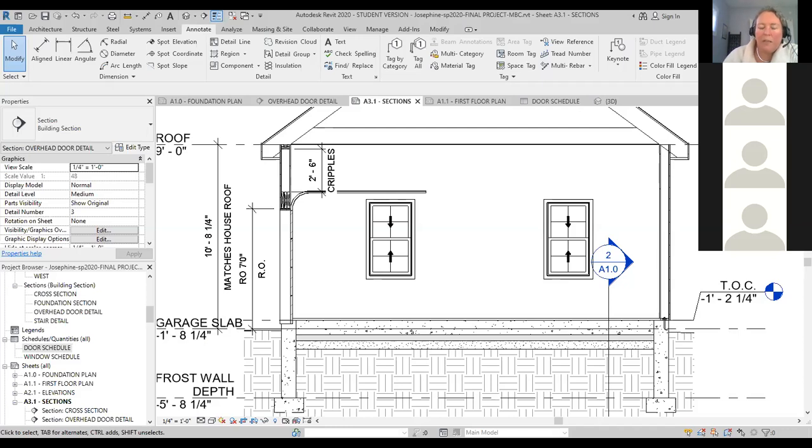Divide that by 12. The minimum wall height would have to be 8.19 decimal feet, as I have to use decimal feet here with that calculation. So we're looking at 0.1875 decimal feet, minus 8 times 12, is about 2 1/4. So it's 8 feet 2 1/4 inches is what we would have to have for a minimum wall height to fit that door, that header, and the 2 top plates. And that probably still wouldn't be enough in the garage for this overhead door to pass.